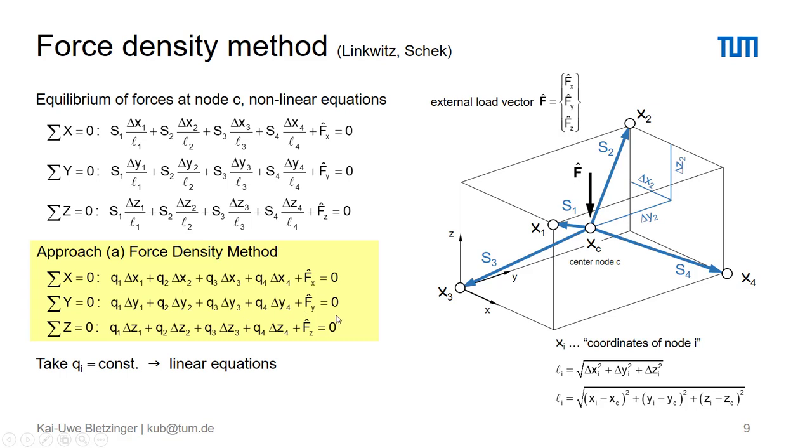That is exactly the force density method. And you see easily that these are indeed linear equations, very simple and robust to solve. And perhaps to refer to Hans-Jörg Schek's paper, where you see an alternative notation of these three equations. Remember perhaps the matrices for the force densities and the node-branch matrix and all these things. But basically, these are exactly the same equations.